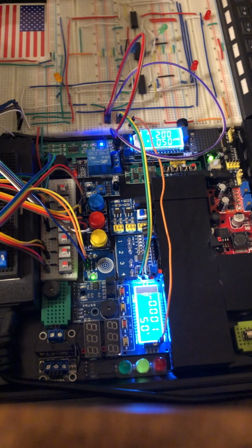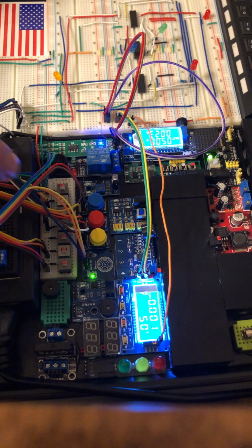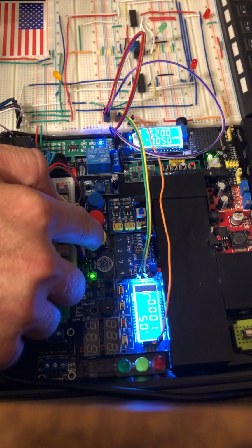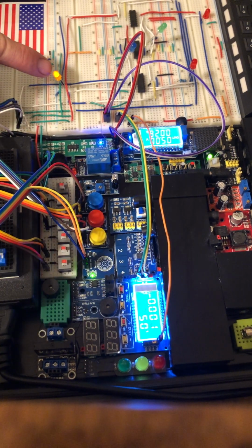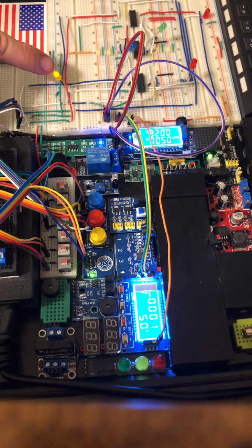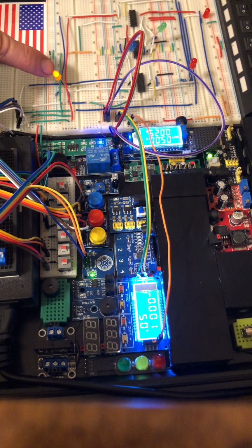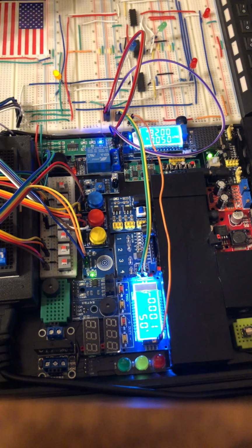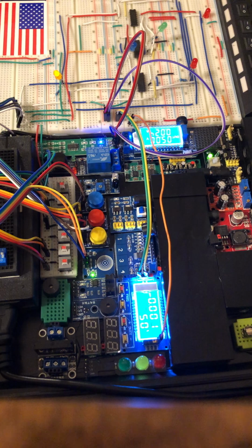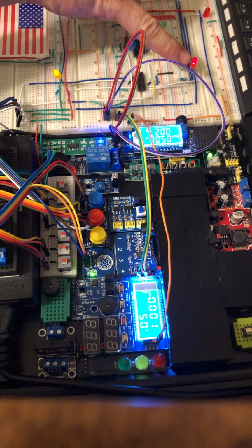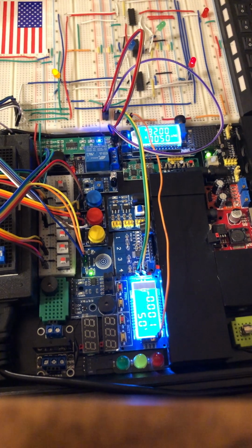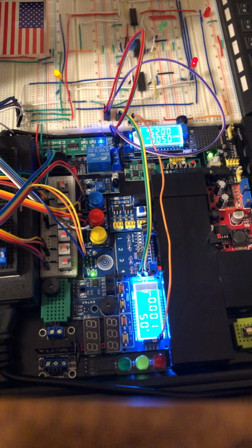We're going to show that our circuit works. First we have our 4 push buttons, and here's push button 1. Now you see that the first yellow LED turned on. That means that we have our 1 right at the end of that first RS latch that we created. In order to push that on the other side of the next AND gate, we're going to need to push another 1 to that AND gate, and that's going to be the red push button here. Now you see that red light turned on once I hit that second push button. That means that that reverberated back to the next one.